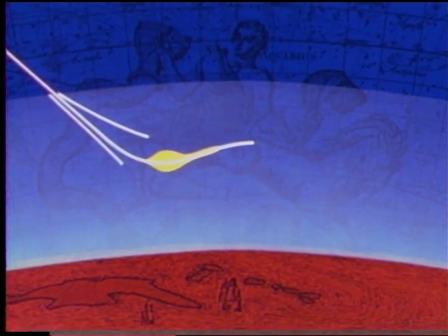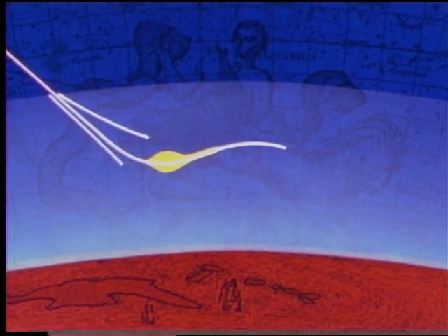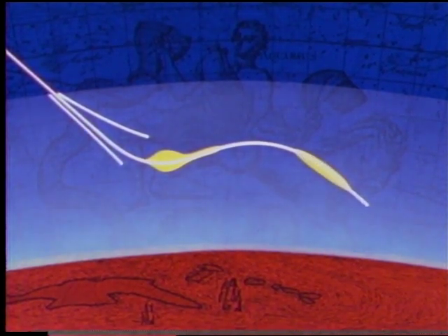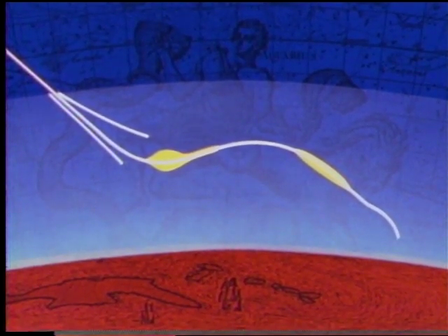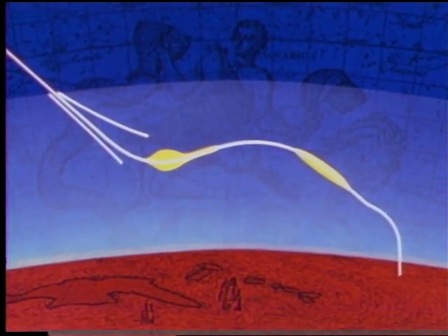As the skip is approached, aerodynamic control is reduced to practically zero. During the skip, the crew will be experiencing weightlessness. The skip will not take the command module beyond the 400,000-foot level. It will then descend, starting its second entry, and go on to the second control period. The entry phase is terminated at the 23,500 foot level, at which point the drogue parachutes are deployed and the spacecraft is committed to its landing point.